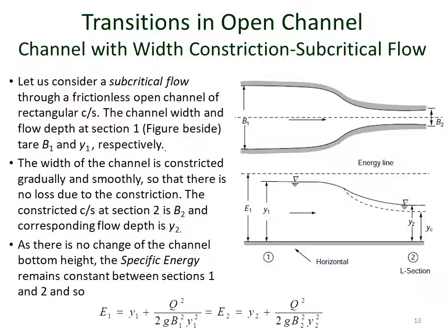Now you can imagine here that there is no change of the datum for the flow, there is no increase or decrease of the height of the channel bottom. There is only change of width of the channel. So the specific energy of the flow is not going to change here. The specific energy will be the same, that is capital E1 at section 1 will be equal to capital E2, which is given by the last equation of the slide.